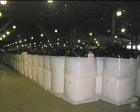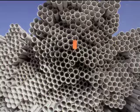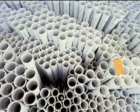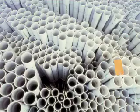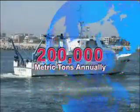CSR products historically have been furnished as a solid dry powder, comprised of grains containing hundreds or thousands of agglomerated primary particles. Powder CSR particles have been successfully used in thermoplastic systems such as PVC for more than 4 decades. Global consumption of powder CSR particles is estimated to be well in excess of 200,000 metric tons annually.